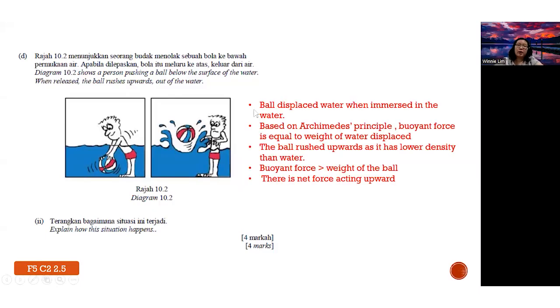Okay, so how do you answer? First, you say the ball actually displaces water when it's immersed in the water. And then based on Archimedes' principle, buoyant force is equal to weight of water displaced. And therefore, the ball rushes up as it has lower density than water and the buoyant force is more than the weight of the ball. Just now I mentioned, right? Your buoyant force is much greater than the weight. That's why the ball will have a net force upward. That's why it rises up.